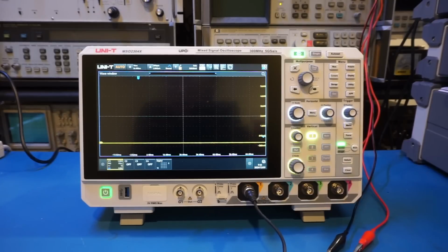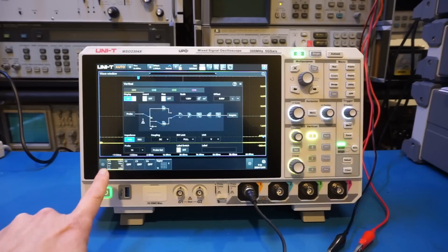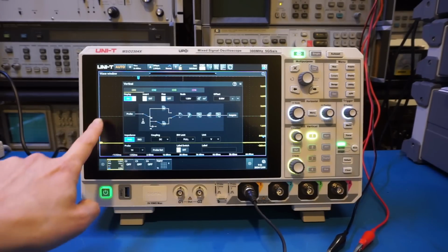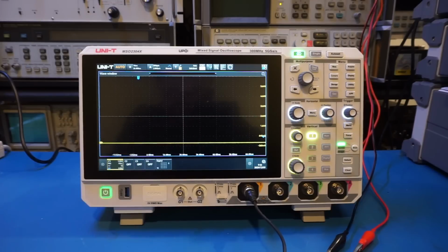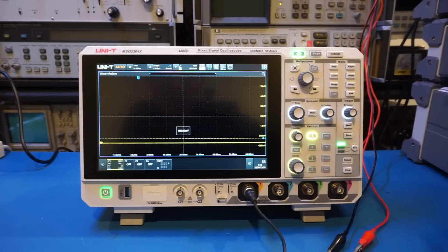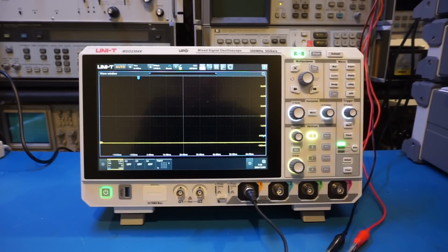Next, let's briefly take a look at the single shot capability of this oscilloscope. For the testing, I'm having a power supply outputting roughly 3.6 volts, and currently the output is turned off. I'm going to turn on the power supply shortly, but let's actually check out the setting here. Right now, you can see here we're using DC coupling, and everything looks good. And you can see here we are setting the trigger point to be roughly around 400 millivolts, and the trigger position is right here. And let's enable single capture.